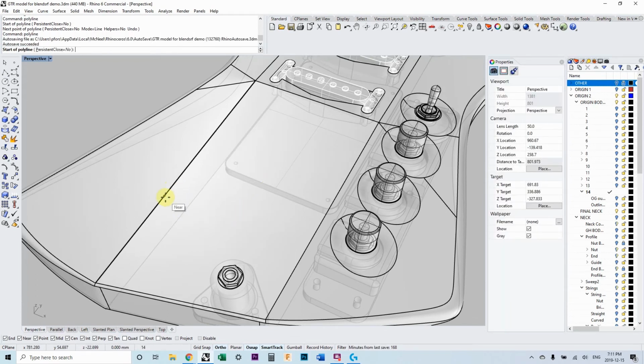And I should note that if you're making these little white points and you accidentally make too many of them, you're not going to be able to find a midpoint anymore, because now there are 3 points. If that happens, you don't need to end the command. Just hit Control twice, and all of them will disappear, and then you can go back and make your points again, or you can go over it and press Control again to get rid of it. So those are 2 different things that you can do. But sometimes there are just too many points building up, and you just need to clear them all out, and you can just hit Control twice to clear them out.